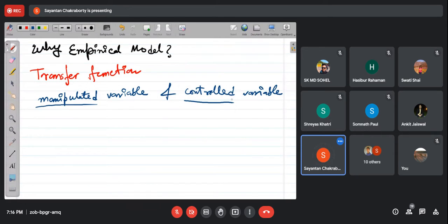Now, for this objective, that is to provide an online regulation algorithm for a process, process identification is very important. And how should this identification be carried out? The identification should be carried out at and around a suitable operating point or set point. Localizing the operation around an operating point is very important so that you obtain a linear transfer function model, right? So that you can apply different tools of control systems to design adequate control of the control loop, right?